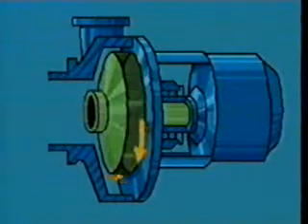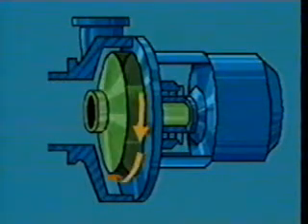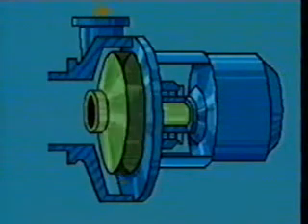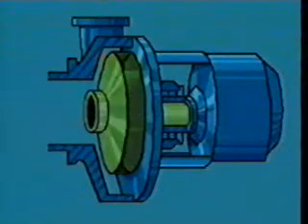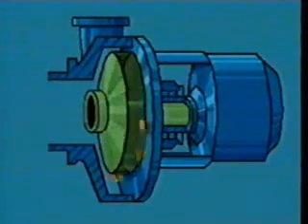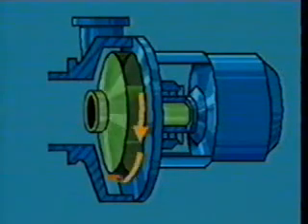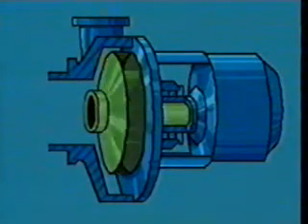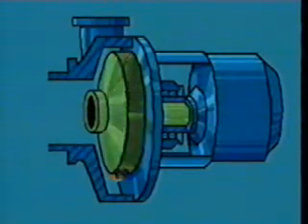How does this relate to centrifugal pumps? In this way. When a centrifugal pump is working, the impeller rotates. Its blades stir the fluid, making that fluid rotate with the impeller itself. It's like a mini hurricane. The circular motion generates enough force to move the fluid away from the center of the impeller to the tips of the impeller blades. The movement of the fluid to the outside edge of the impeller creates a suction at the eye of the impeller that draws more fluid into the pump.